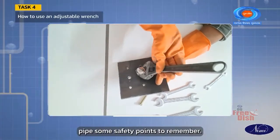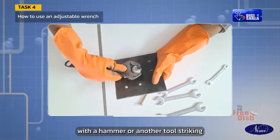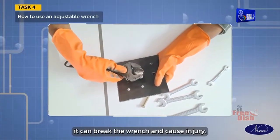Some safety points to remember. Never strike the wrench with a hammer or another tool. Striking it can break the wrench and cause injury.